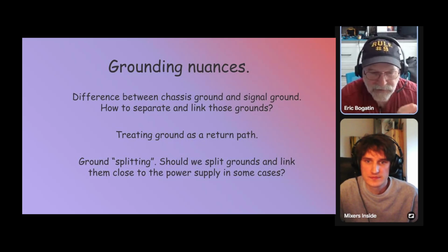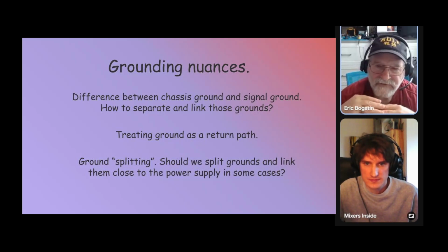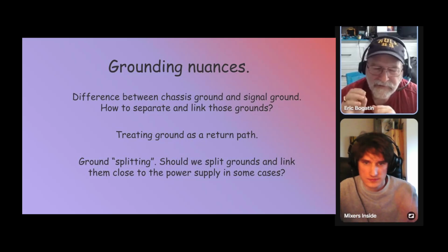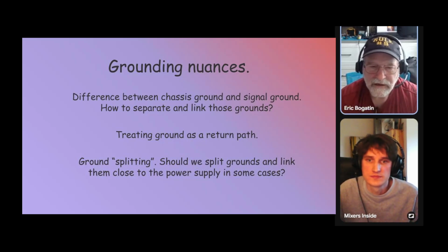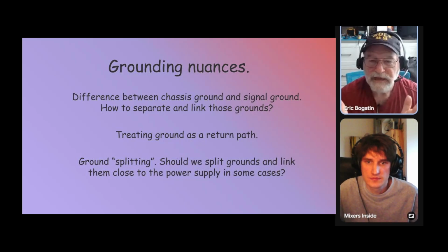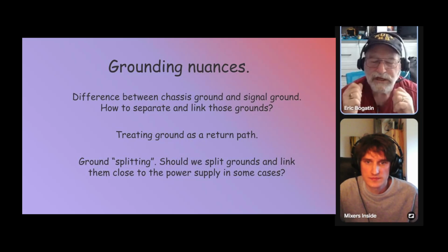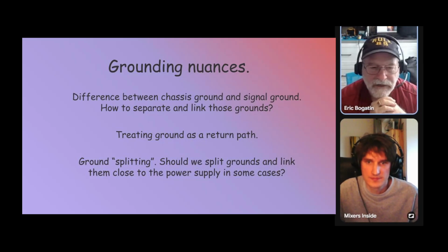When we turn the schematic into the layout, if there is no current in the physical interconnects of the circuit ground, typically the ground plane, then there's no voltage drop across it. And so every point on that ground plane is going to be the same voltage, and that's a good reference to use wherever we need it in the circuit.